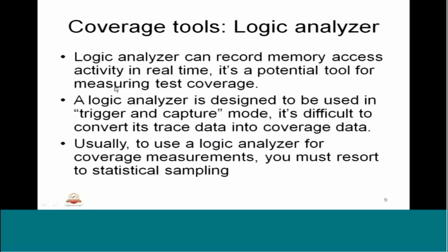So what it does is we have various test hooks within the embedded system, and the test hooks will record different data in a dedicated piece of memory, and that memory can be recorded with the help of this analyzer. That analyzer is called a logic analyzer, and there are logic analyzer probes that will be hooked into the memory, and with the help of probes it will acquire the data in real time and will provide the coverage results and reports.